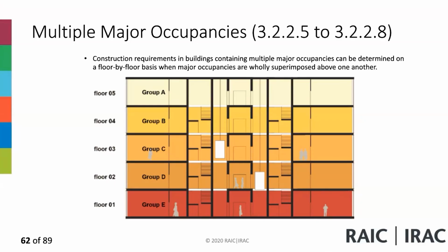Okay, a fire separation is a tight, continuous construction that has to have protected closures in it. If you have an opening, you need to protect it unless it's a permitted opening by some other provision in the code. Once a fire separation has a fire resistance rating, it has to be tested and meet the testing criteria for fire resistance, and you allocate to it a certain rating, whether 45 minutes, 1 hour, 1.5 hours, or 2 hours.